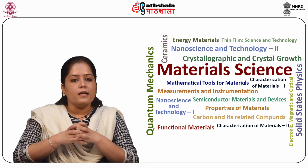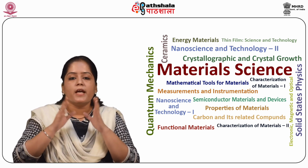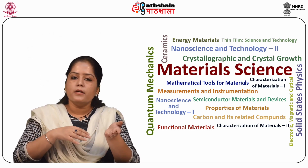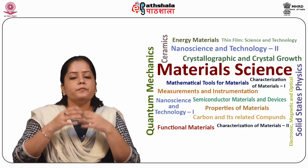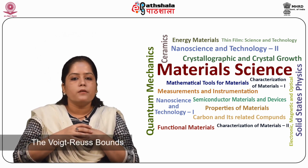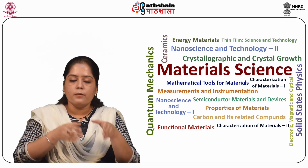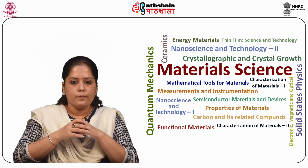Then we discussed that the elastic constants of the polycrystals can be predicted as for the composites using the rule of mixtures, with the upper and the lower bounds of the bulk modulus B and the shear modulus mu being given by Voigt-Reuss bounds as follows, that is m equal to m1 v1 plus m2 v2 and 1 by m equal to v1 by m1 plus v2 by m2.